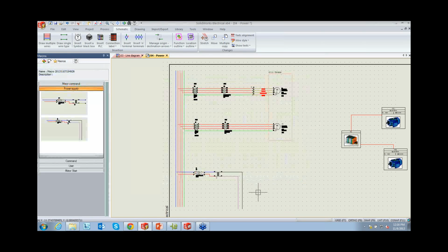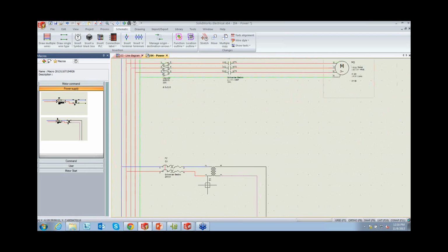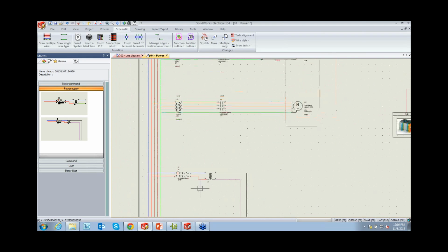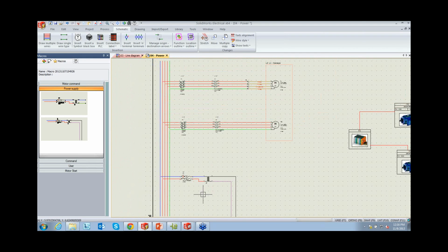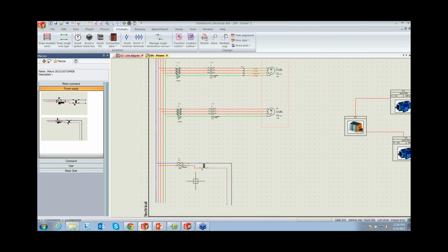So basically, you can use the same name for the component if you use it in all the projects, like your power supply, for example. You might use a whole bundle of a power supply and it's always named the same. But if you want to change something like using terminals, it'll let you change that. Yes, it would. That is great. So yeah, I've had that before. I've been using this feature quite a bit with reusing circuits. And it's always been a pet peeve of mine that I want certain wire numbers to remain the same or certain devices to remain the same.